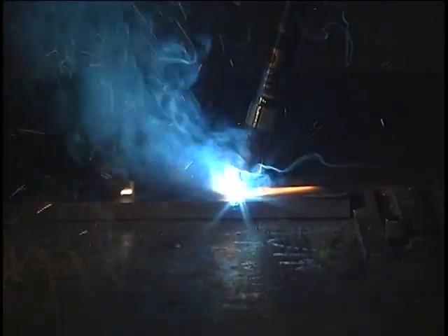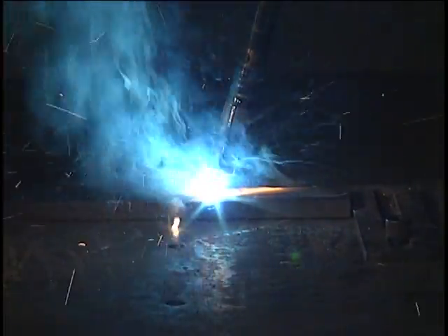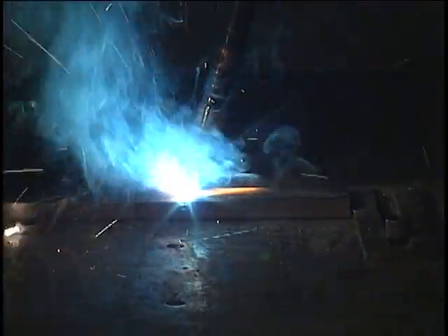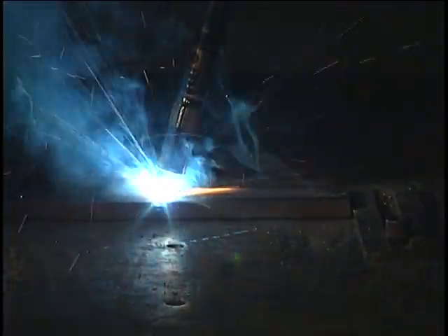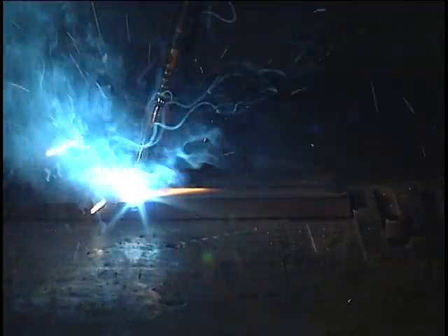When the appropriate arc voltage relative to the welding amperage is selected, the arc is stable, creating a uniform sound. The setting of the arc voltage is important because it affects the arc stability and the bead appearance. The correct arc voltage selection relative to the welding amperage selection makes the arc stable and decreases the spatter.